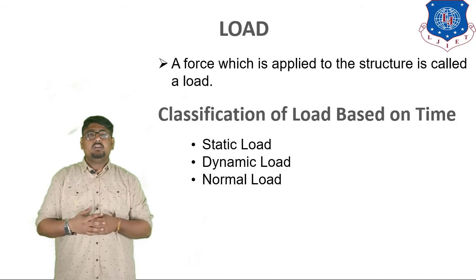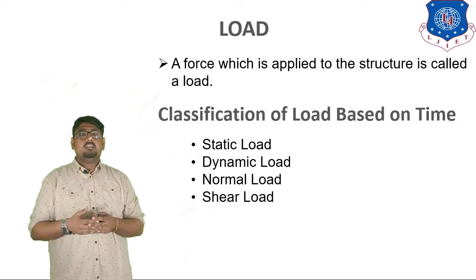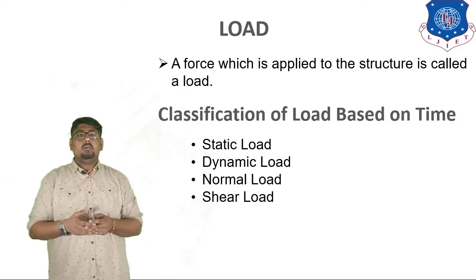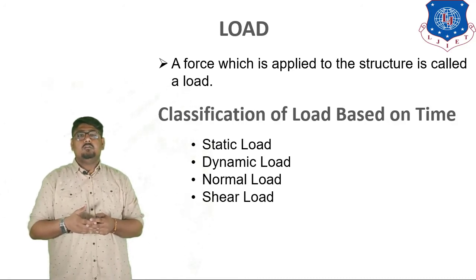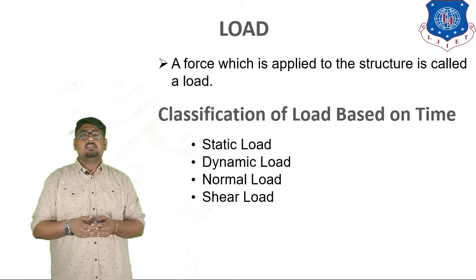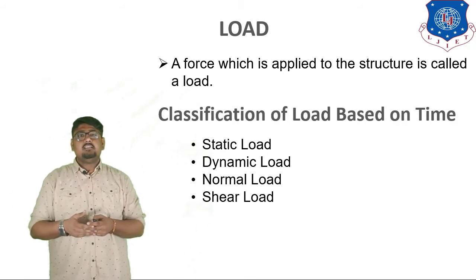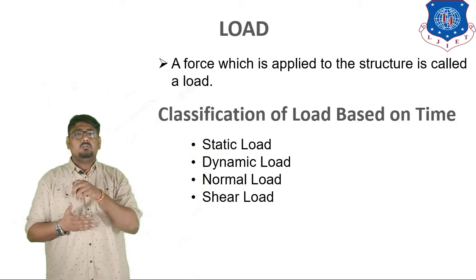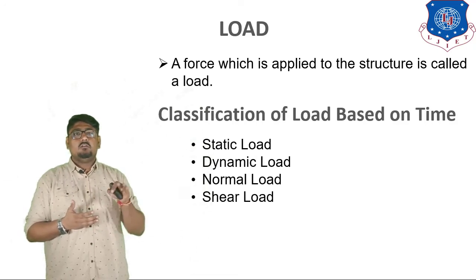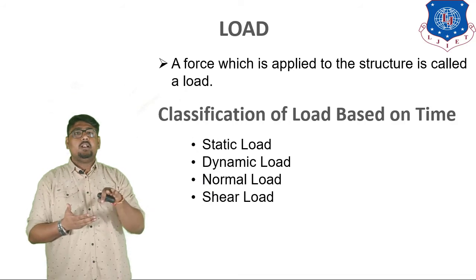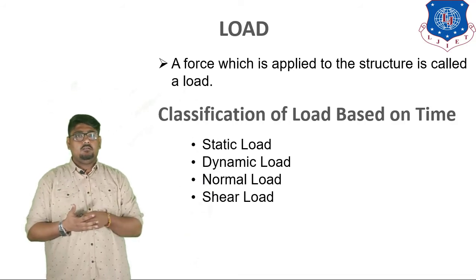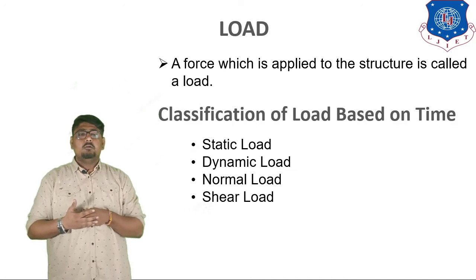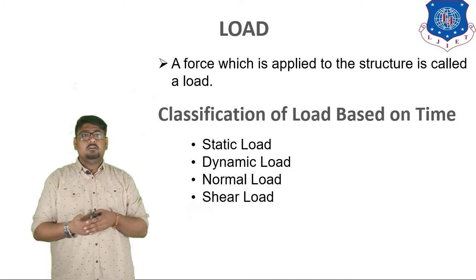Now next comes the shear load. It is a load which tends to produce a sliding failure of a body along a plane parallel to the direction of the load, or the forces, and is known as a shear load. Let us take the example of water flowing from a higher level to a lower level. There is constantly a shear load applied on the molecules of the water particles. Such a kind of load is known as a shear load. We will discuss it later.